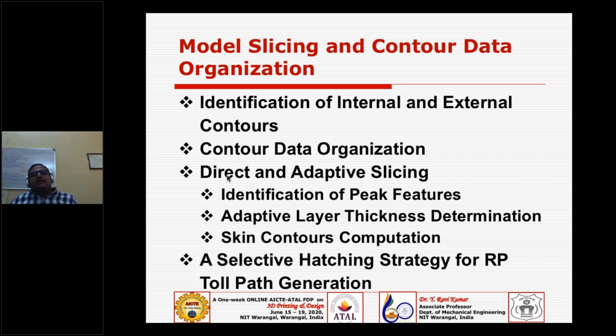Let it read from the .prt or .part file. Then from the direct CAD to the G code, you bypass STL. You can save a lot of data errors, you can bypass the errors. Why? Because STL is not a 100% complete representation. It's a mesh.